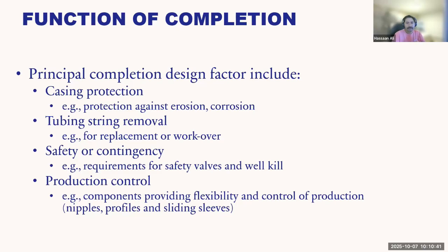Tubing string removal. You want to have the flexibility of removing your tubing string for the workover, or if you want to change components, you want to have that flexibility in your completion design. Safety and contingency. Safety in terms of deployment of safety valves, subsurface safety valves or surface safety valves, and then your ability to kill the well if somehow it is coming to a point where your bottom hole pressure is increasing to a factor where you cannot control it.